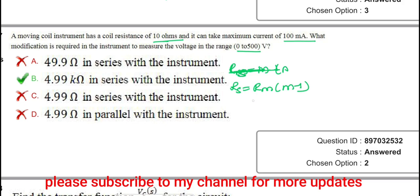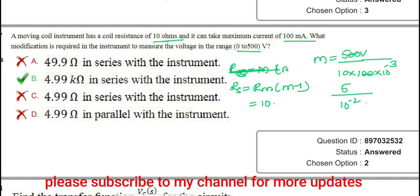Now what is the meter resistance? It is 10 ohms, given. We need to find M. So M is nothing but maximum voltage divided by meter voltage. The maximum voltage here is 500 volts. Now we need to find the meter voltage. So it is 10 ohms into 100 into 10 power minus 3 current. Now this 10 will go, so 5 divided by 10 power minus 2, so it is going to be 500.